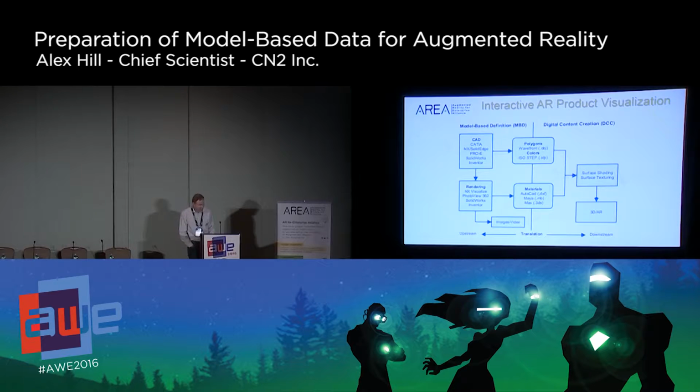So in the case of interactive AR product visualization, we can export out of almost any CAD program to DCC formats, such as Wavefront, or if we want to preserve colors that we may have colored our product, we can use something like STEP. And in the case of many of the tools that use photorealistic rendering, we can export those to native DCC formats.